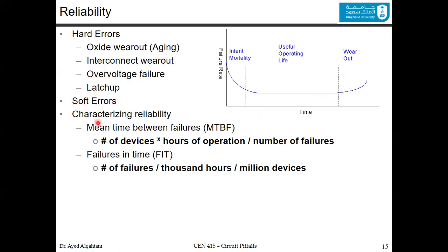Now, generally, we can characterize the reliability as the mean time between failures, or the MTBF, which is calculated as the number of devices times the hours of operation divided by the number of failures. Or we could measure it as failures in time, or FIT, which is the number of failures per thousand hours per million devices. Now, we will talk about these three.